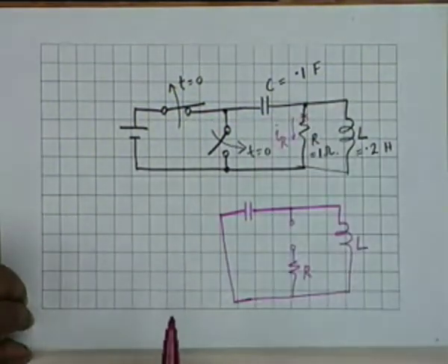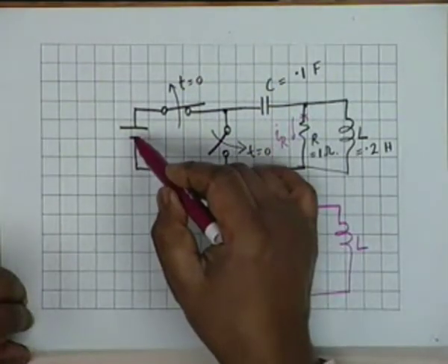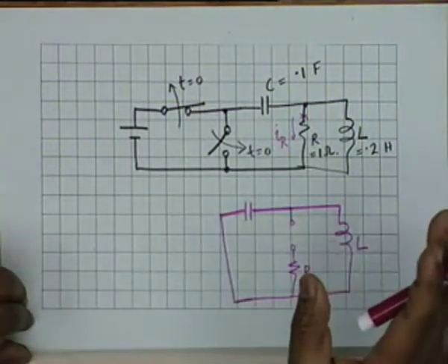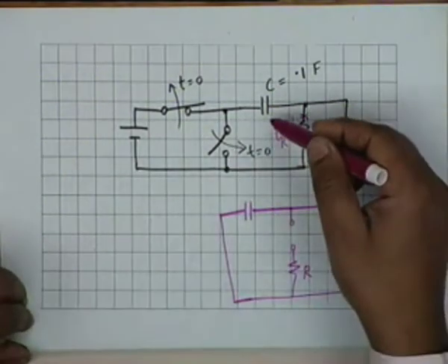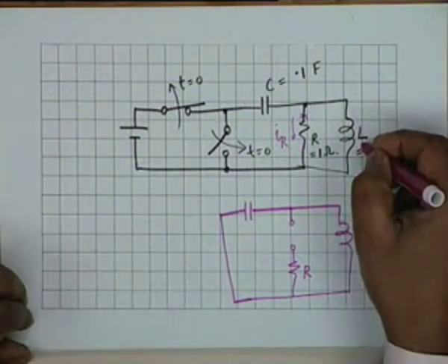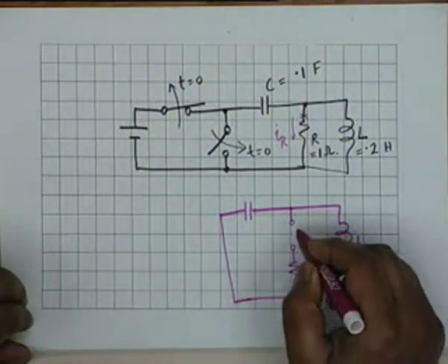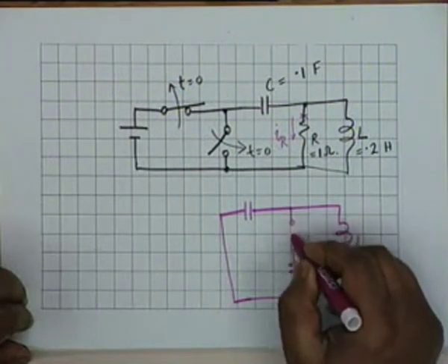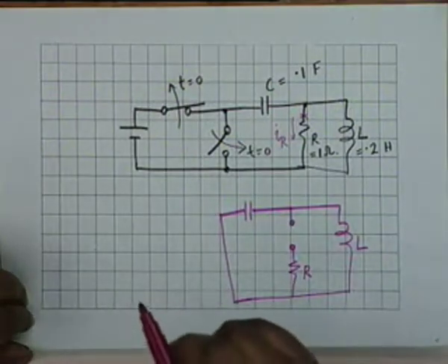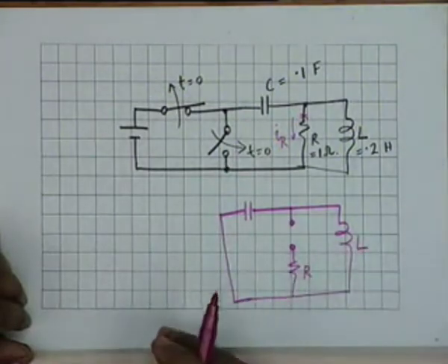There is an initial voltage on the capacitor, which would be exactly equal to the voltage at the source. That is part of the initial condition which you can find out. That is Vc(0-) equal to Vc(0+), and IL(0-), which is equal to 0, equal to IL(0+). But since we are trying to find the current through the resistance R, we find the impedance between these 2 points. We make an artificial break, find the impedance and then find its zeros.